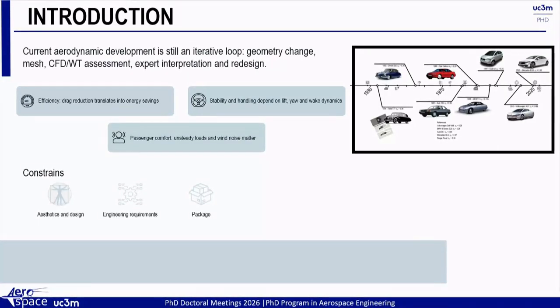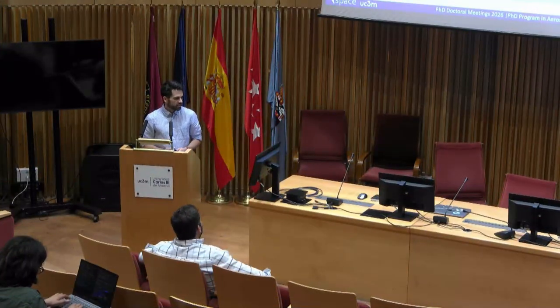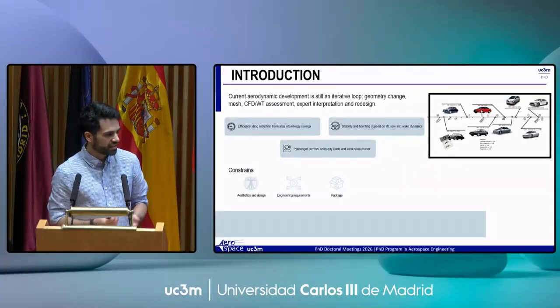And what we are going to talk about today is automotive aerodynamics and why this is important. Basically, we've got three main reasons. One is efficiency, so an aerodynamic car consumes less, happy days for everybody. Stability. The aerodynamic forces can make the handling of the car unstable, so aerodynamics keeps you safe. And passenger comfort, because if there are loads, the wind noise could be quite stressful